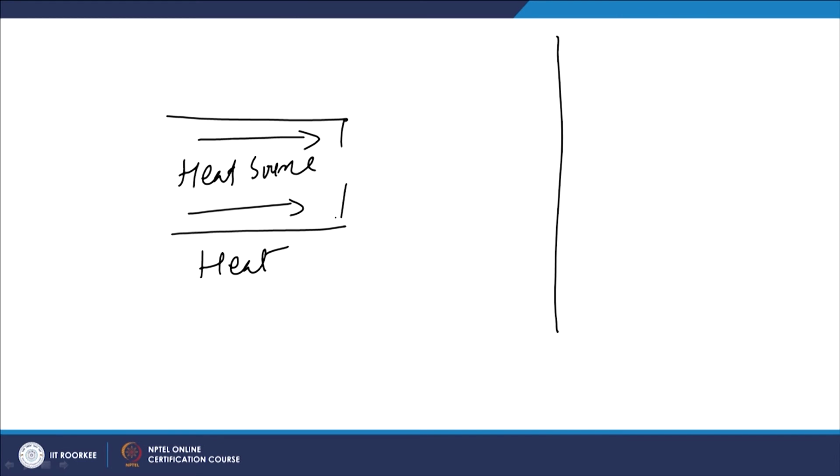Here the material to be applied onto the surface is brought to a molten or partially molten state, and then it is accelerated towards the substrate by suitable means, such as a high velocity jet. These molten or semi-molten particles, when they impinge, get flattened after impingement with the substrate surface, and then they get solidified.